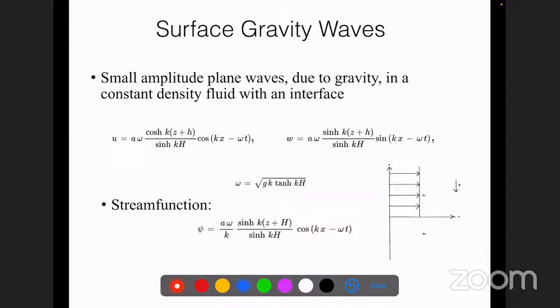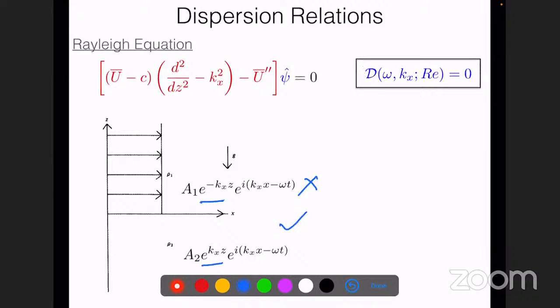So whether you take the deep water, whether you take this finite depth problem, or you take the deep water limit of an exponential e^(-kz), the fact is in the vertical direction, normal to the direction of propagation, the fluid velocity, you forget the top layer, you just look at the bottom layer. The fluid velocity is an exponential function of the vertical coordinate, which means as the wave propagates, as a crest goes and a trough comes and another crest comes, and imagine you were being transported by this crest and trough. So you go forward, then you start coming backward. Now, when you are going forward and when you are coming backward, in the top region and the bottom region, the fluid velocity in the x direction is not the same. There is a factor of e^(-kz).